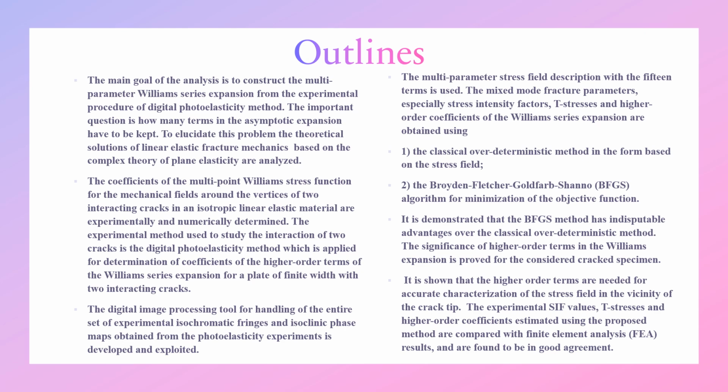The mixed mode fracture mechanics parameters, especially stress intensity factors, T-stresses, and higher order coefficients of the Williams series expansion, are obtained using two methods: the classical over-deterministic method in the form based on the stress field, and the Broyden-Fletcher-Goldfarb-Shanno algorithm for minimization of the objective function.